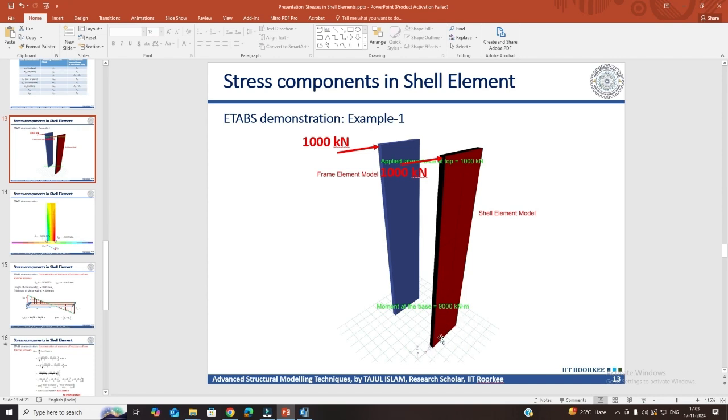For example, if this shear wall is lying above a mat which is very large in area and thick, then definitely its rigidity will be much higher compared to when it is lying just above the soil. And in case of soil, suppose you are trying to construct a shear wall directly on the soil, then definitely you have to determine what is the stiffness of soil beneath the shear wall. There is no other option.